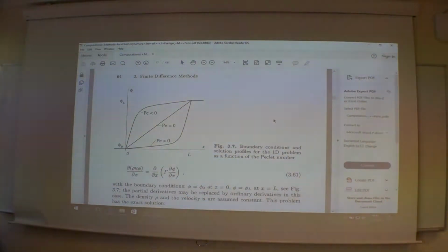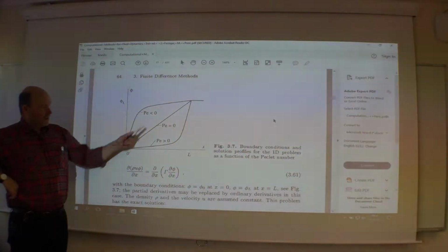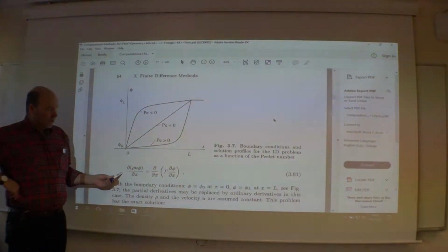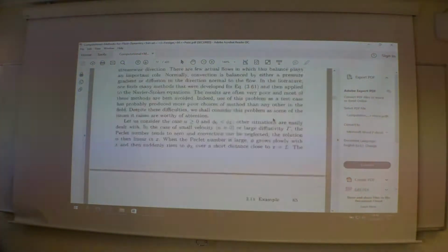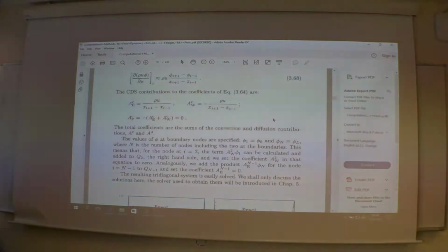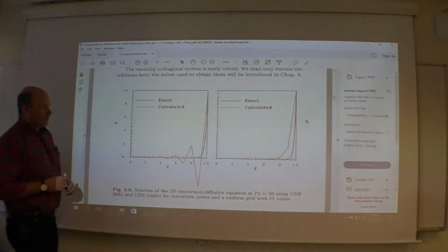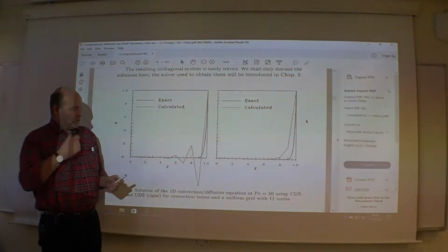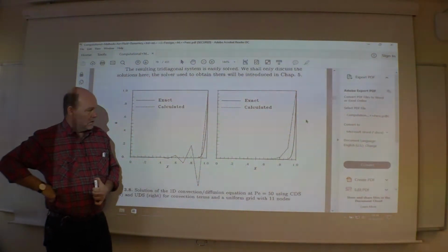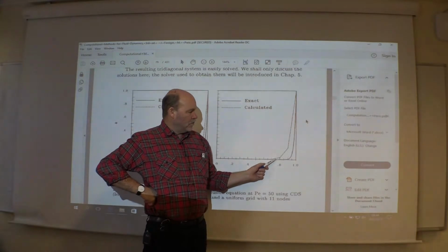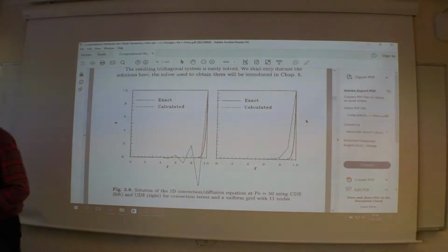Yeah, this was the classical example we looked at earlier. Exactly the same layout, and yes, you have an analytical solution to this one. And yes, if you violate the stability criteria here, the cell Reynolds number is bigger than 2, then central schemes give you very unrealistic results. The first order upwind gives you a result, yes, but with a very big error.